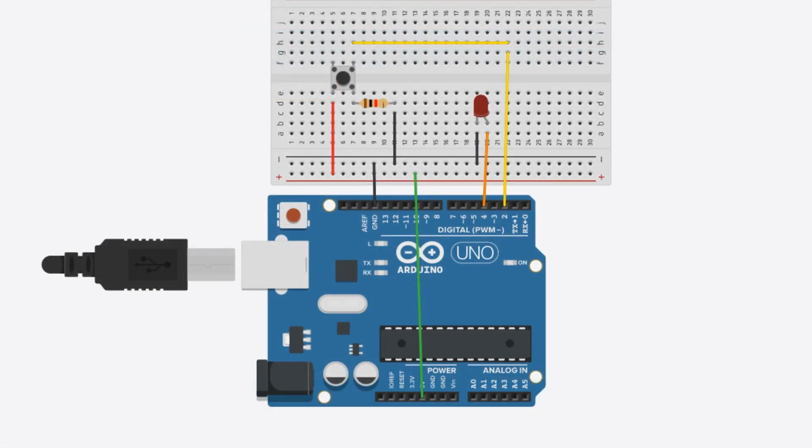Here is the layout for the example. Note the 5-volt current and grounding provided to the LED, which is the output, and button, which is the input, through the power rails on the white breadboard. It is important to understand that the 5 holes in the individual numbered rows, or terminal strips, on the breadboard are wired together on either side of the center divider.